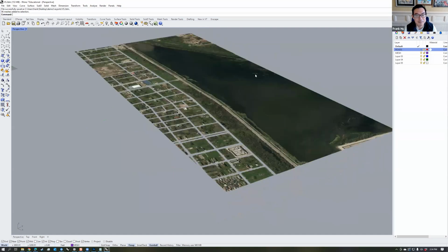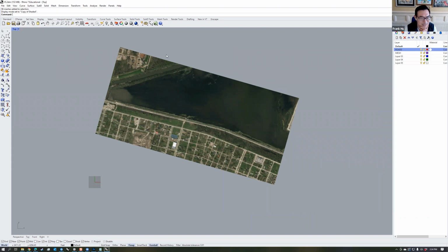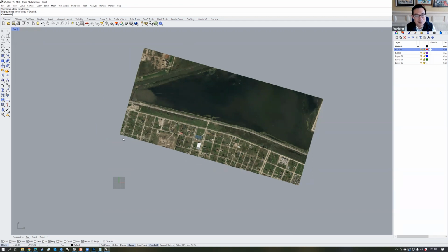So that's optimized now. In the past, I've done this whole Grasshopper thing where you take your contours and turn it into a surface. I've been really stupid the whole time. There's actually a way easier method to create a surface out of all this. First thing you do is take this image here and rectify it so that it's square with the image.